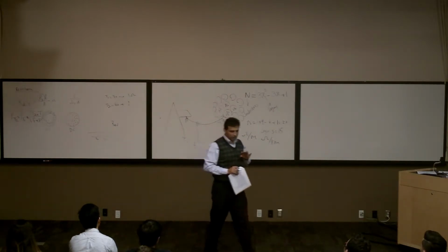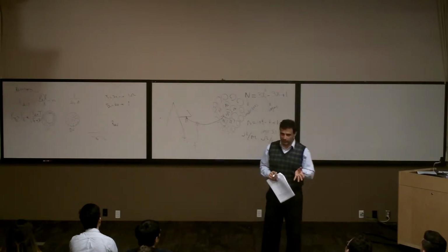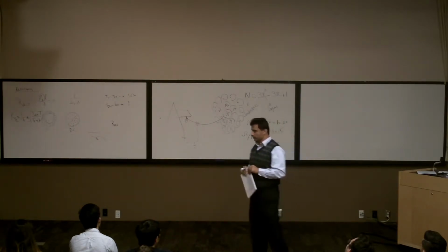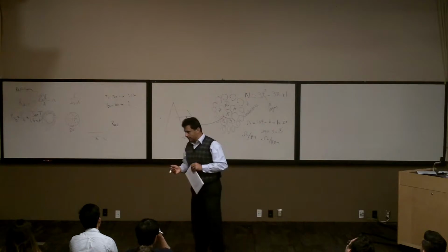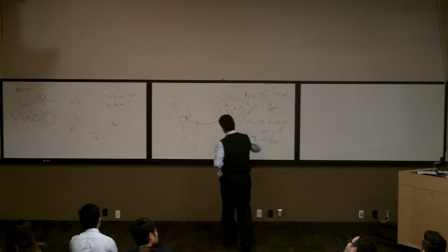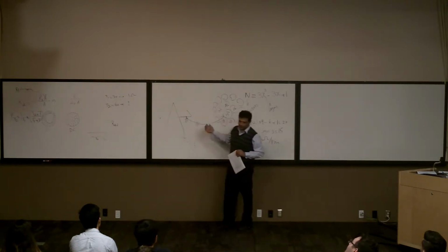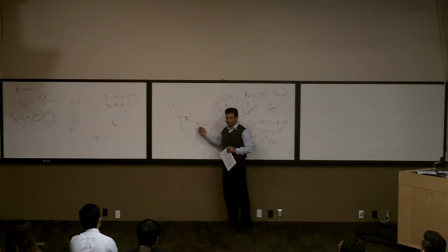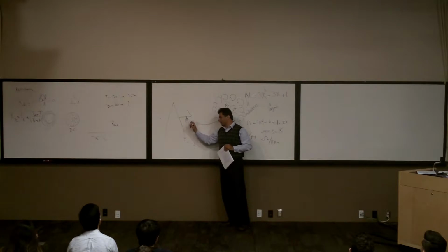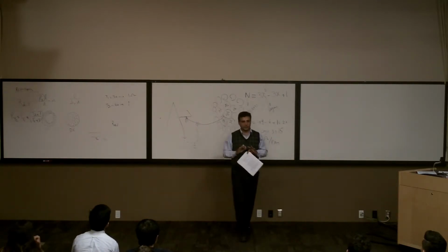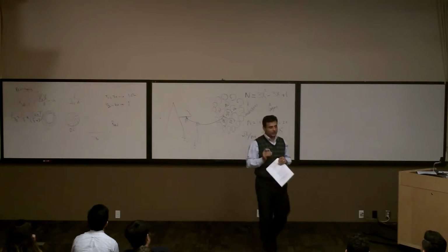And second of all, it's very difficult to calculate. You know what I'm saying? It depends on the environment condition. It depends on what temperature you are at, how much humidity we have, how far we are from the ocean, how much salt there is, and how often they clean the insulator. So it's very difficult to calculate that one. But they call it conductance.